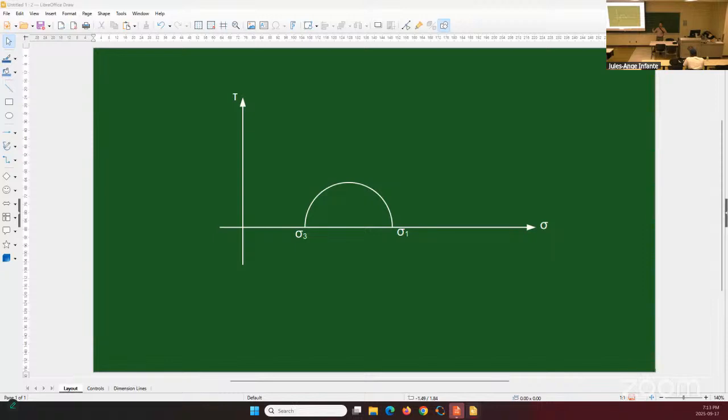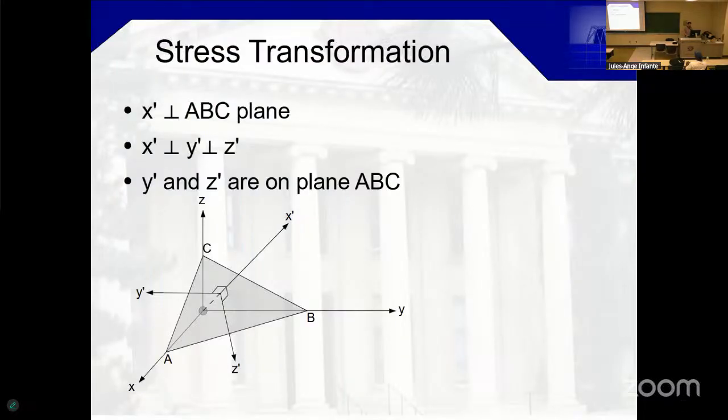By contrast, in the direct shear box, we know what the failure plane is. We know what the shear strength is on the failure plane, but what we don't know is what sigma 1 and sigma 3 are there. Okay, we have only one point on the Mohr circle. But in the triaxial test, we always control the full Mohr circle. So we will often be interested in knowing the principal stresses, because that simply defines our Mohr circle. We can easily draw it and extract other information from it.